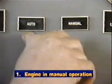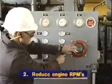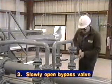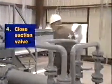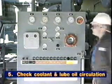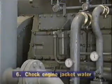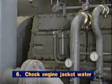First, put the engine in manual operation. Then reduce the engine RPMs. Slowly open the bypass valve. Next, close the suction valve. Check to be sure coolant and lube oil are circulating. Also make sure there is engine jacket water circulation, and note unusual noises or vibration.